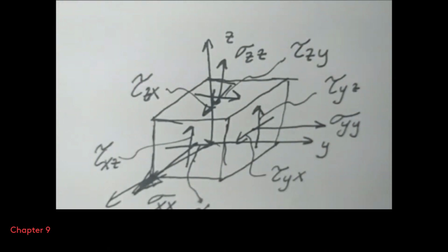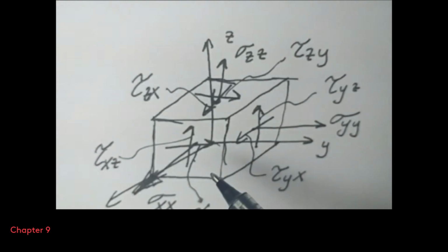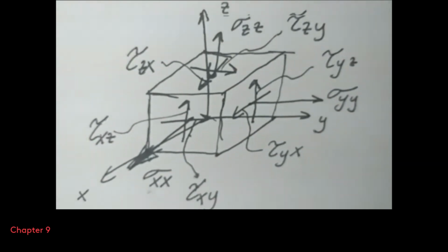We also have 3 others. We have stresses on the other faces, but they are equivalent to these values. Let's assume that they are equivalent. But in fact, we have 9 stress components. Now, certainly, the tangential stress components will try to rotate this unit cube, and conservation of momentum will tell us that tau xy has to be equal to tau yx.